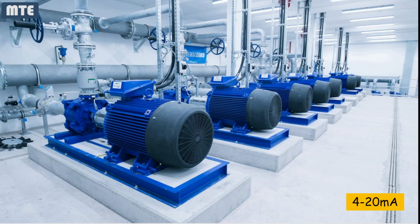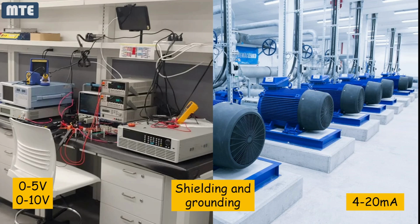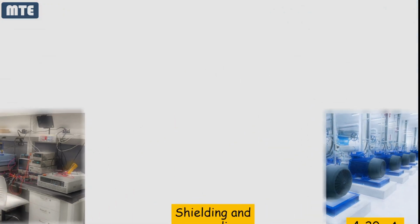Imagine a pressure sensor monitoring a pipeline. If the sensor is located hundreds of meters away from the controller, a 4 to 20 mA signal would be ideal to avoid signal loss and interference. Ultimately, the choice of signal type depends on factors like distance, noise, required accuracy, and the specific characteristics of the application. In either case, proper shielding and grounding of signal cables are essential to minimize interference and ensure accurate readings.